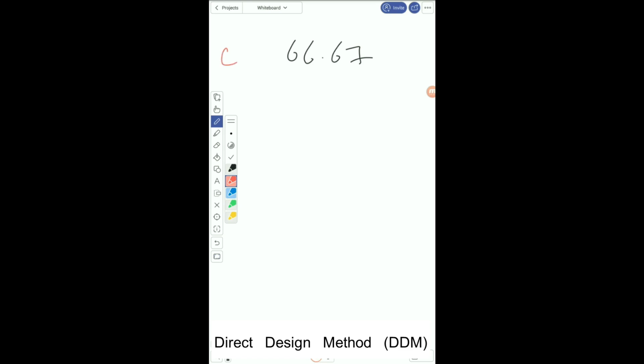It was the moment that is coming to column strip, and now this moment has to further divide into two things what we discuss. One will gonna go to column strip slab, another will gonna go to beam. We already have discussed that the percentage to column strip slab will be only 15% and it will be 85% going to beams. So we're going to do the calculation here.